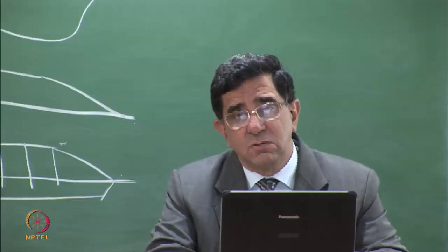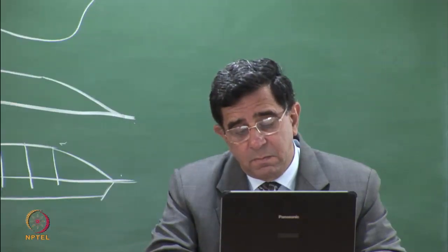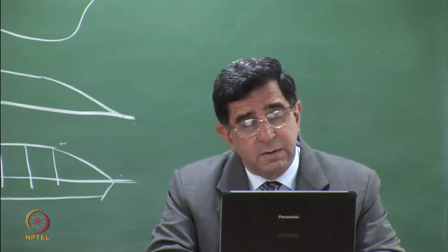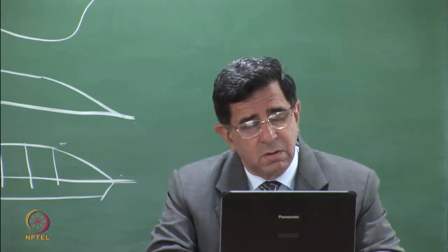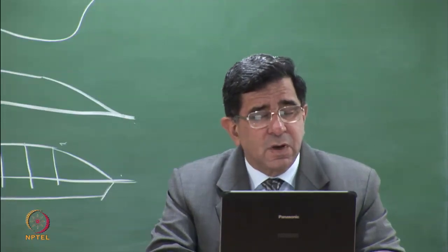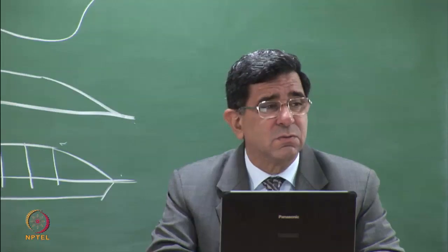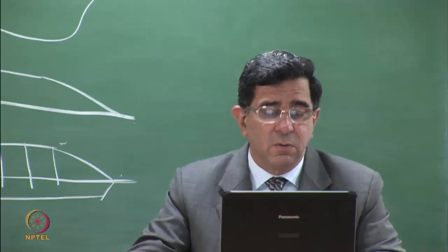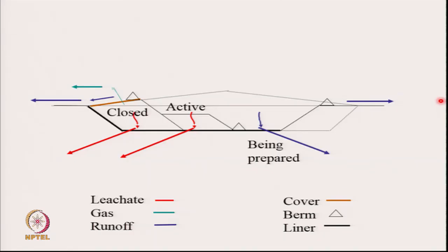Today, if I just talk to the Ankleshwar landfill people, the rate of treating a liter of water, I think it's ₹4 or something for them. So it's an expensive thing to do, to treat so much leachate once it is generated. So keep it out, have the slope this way, the surface runoff, have the slope this way, the surface runoff. Only here you will get leachate. This leachate, because it is closed, will be much lesser than this leachate because this is active. Agreed?